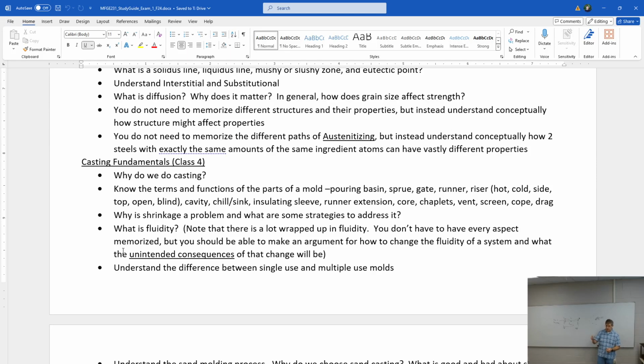Yes, that's called normalizing or annealing, when we heat it back up and distribute things and then cool it back down. And so we can get lots of different shapes and sizes of the distributions of interstitials, depending on how we cool it and what our temperature process is.